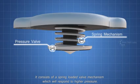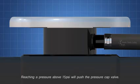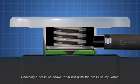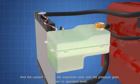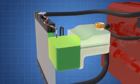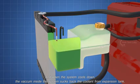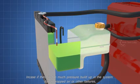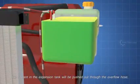It consists of a spring-loaded valve mechanism, which will respond to higher pressure. Reaching a pressure above 15 psi will push the pressure cap valve, and the coolant flows to the expansion tank until the pressure goes down to operating level. And when the system cools down, the vacuum inside the system sucks back the coolant from the expansion tank. In case there is too much pressure buildup in the system, due to trapped air or other failures, the coolant in the expansion tank will be pushed out through the overflow hose.